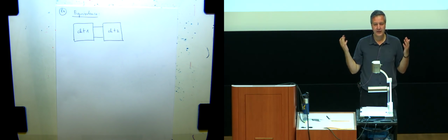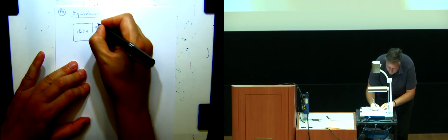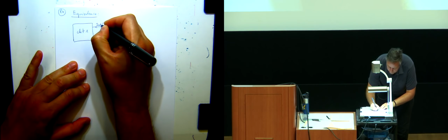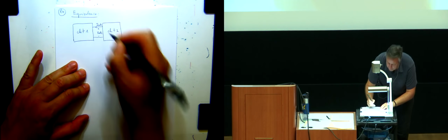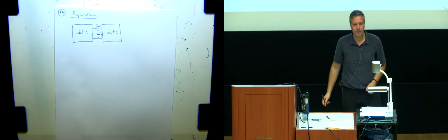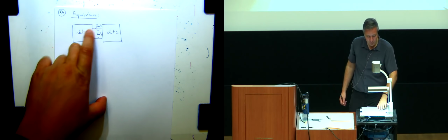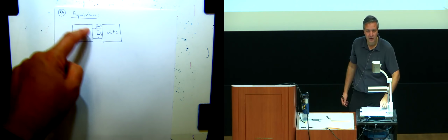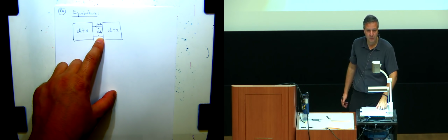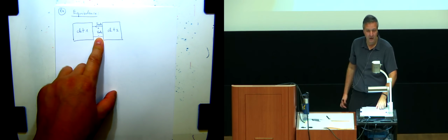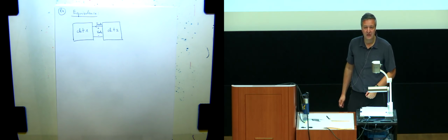All that these circuits care about is what is this current, I out 1, and what is this voltage, V out 1, between them. If I put some other circuit here, and it produces the same values of current and voltage, this I out 1 and V out 1, when attached to this circuit, then these two circuits are equivalent.